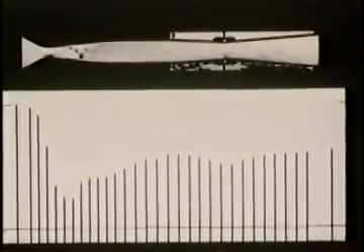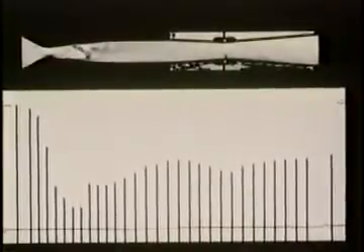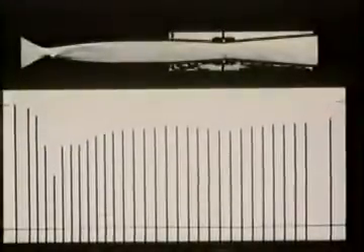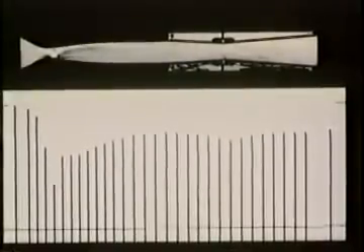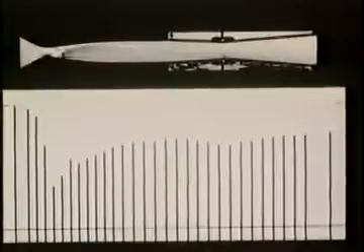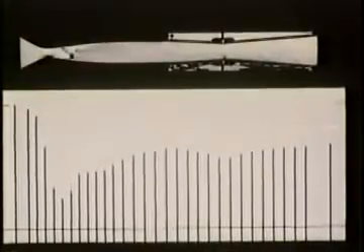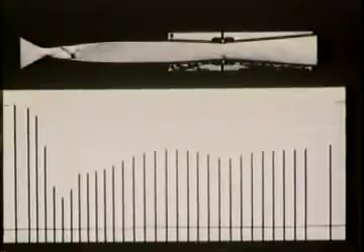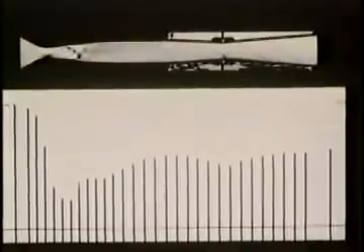This time we'll keep a record of the continual decrease in pressure and also density of the subsonic flow through the second throat. Since the mass flow is fixed, because the first throat is choked, and since the area of the second throat is constant, the fact that the density is going down means that the velocity at the second throat must be going up. Finally, the second throat goes sonic, or chokes, and the channel is blocked.